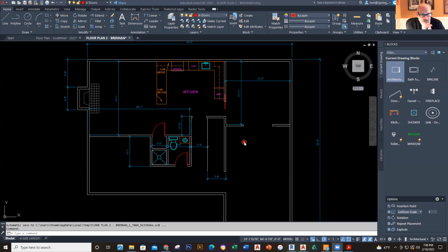Well, the only thing I would say is, did you use the template I gave you? Yeah, the text works in any other drawing, but when I open it with the template with all the different colors for the doors and the walls and everything, for some reason I can't get text boxes to open. Well, if the text is too small, you can just use the scale command and make it larger. I don't think it's too small. It literally just shows a tiny dash.